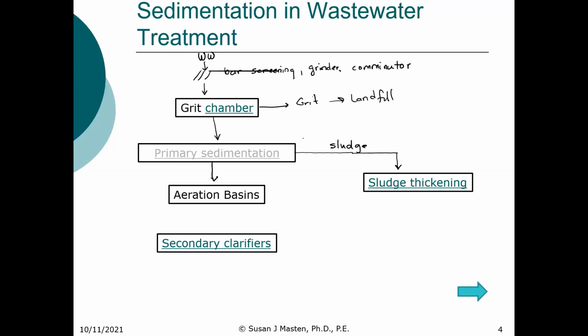And our effluent then goes into an aeration basin, which we'll talk about later in the semester. Oxygen is added to that. What we're doing in that system is using microorganisms to degrade the organic material. So we're looking at converting the complex organics into CO2. Okay.